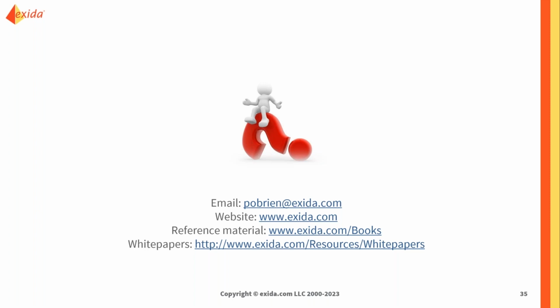Okay, so the next question I have here is, is there a difference between proof testing and functional testing for SIF loops? And is there a simple diagram or an animation to show the differences? So I'd say I don't have an animation off the top of my head, but I've got a couple of good examples that can help to illustrate the differences. So the first is, a lot of the times a functional test might be done just to show that a safety function works, whereas a proof test is specifically trying to find any undetected failures in the safety system.